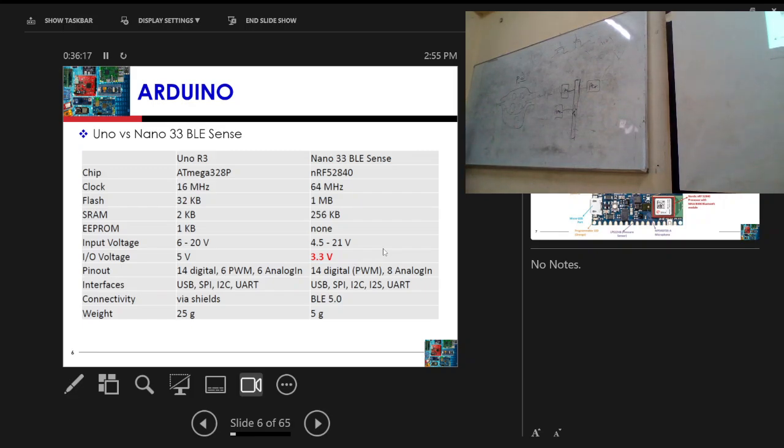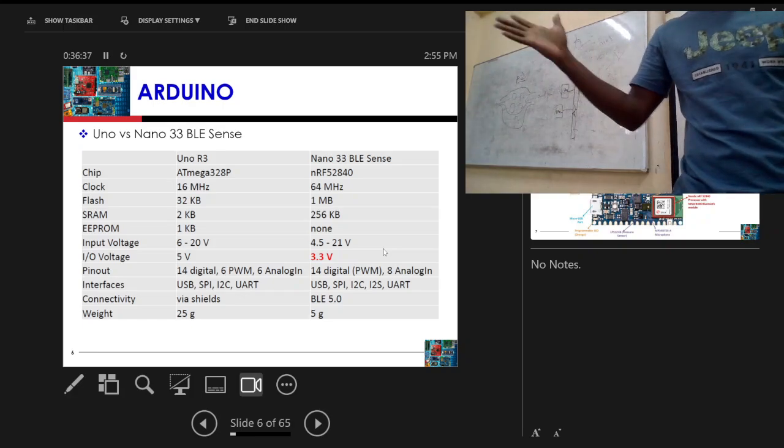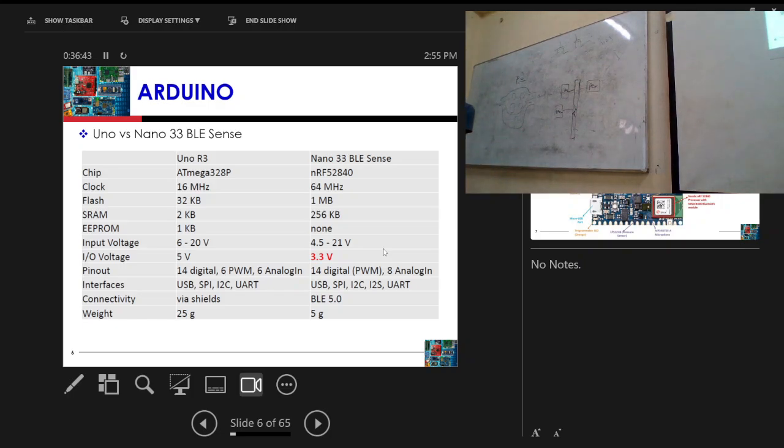What is the amount of time it takes the signal to travel from here to the output, the input from this to the output, and then the input from this to the output? Then it takes the highest number. So that is how we calculate frequency in a digital system. It looks for the longest path from the input to the output. Understood? So the time is fixed, and the frequency, as the guy said, is equal to 1 over time. So that simply means that if the time is long, what happens to the frequency?